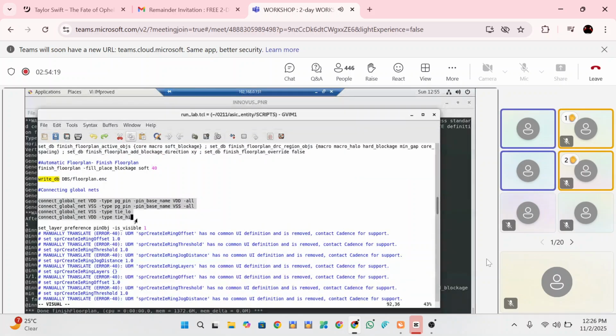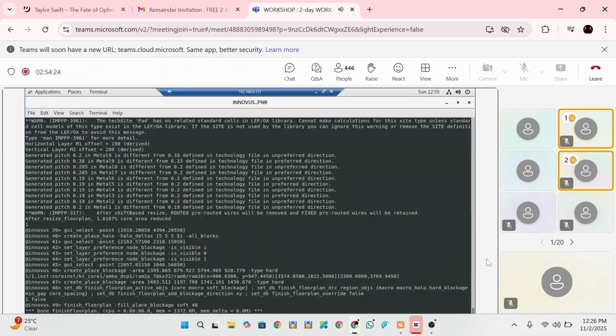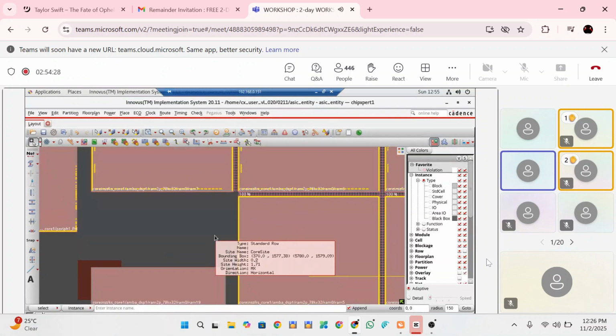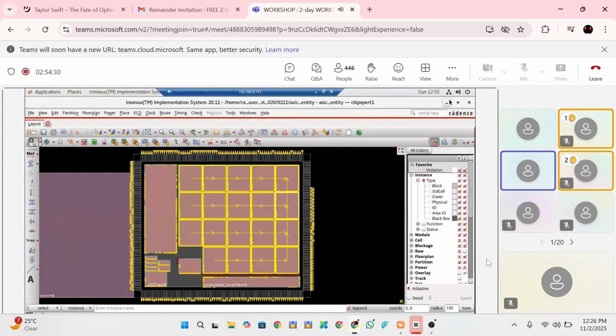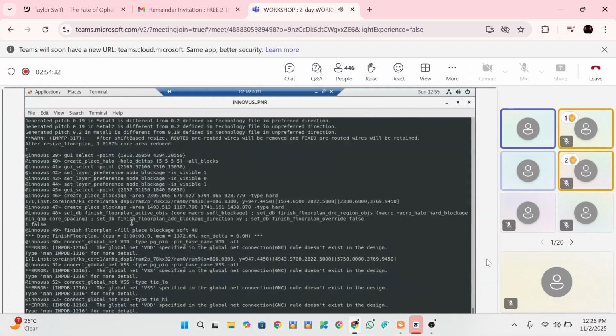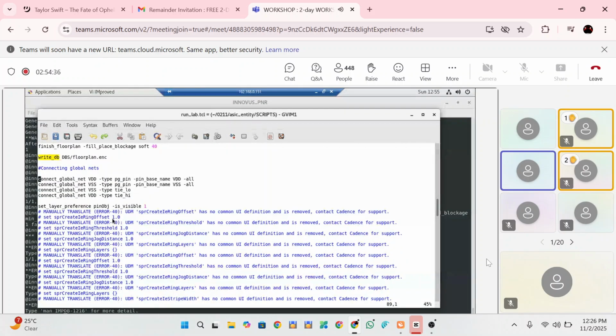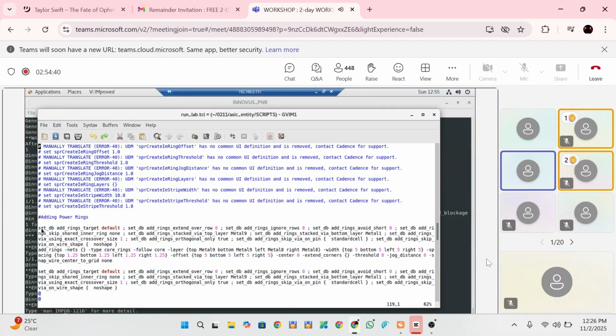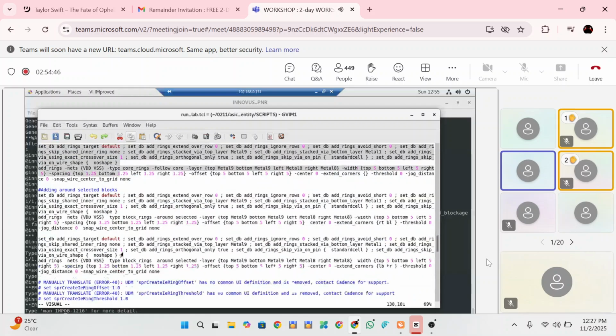Why will the halo not allow placement? The halo itself will not allow placement. That is why the halo is used. We are not placing cells very near the standard cells because standard cells are very sensitive and prone to the heat that gets generated in the ramps or short circuit or whatever it may be. We should also sometimes leave a small space for routing resources.